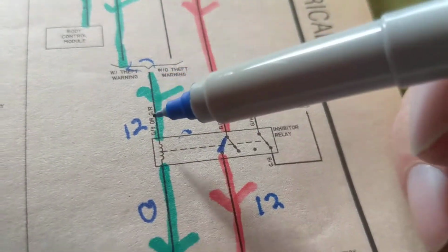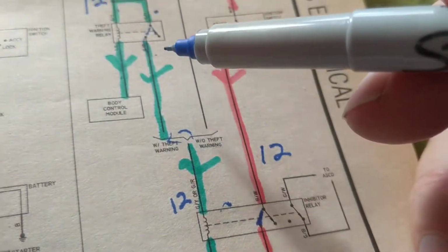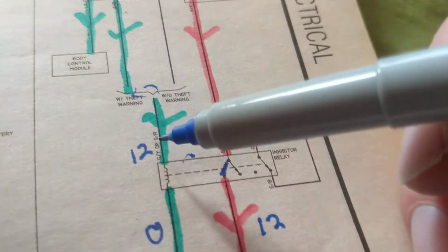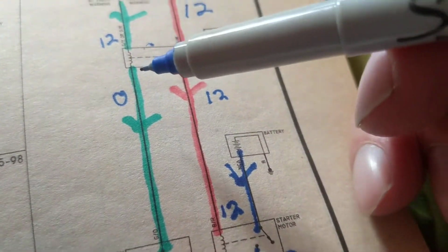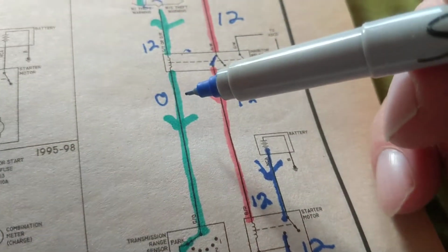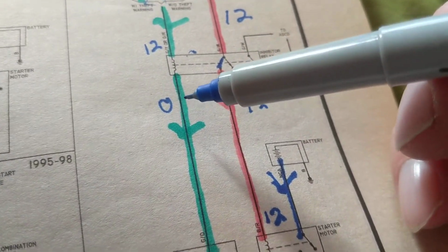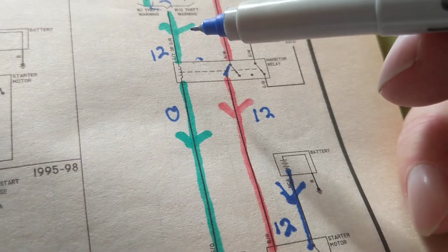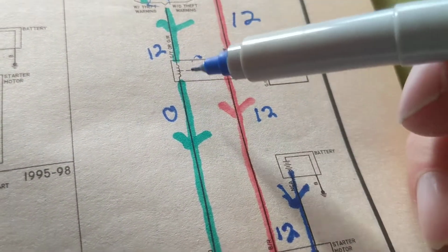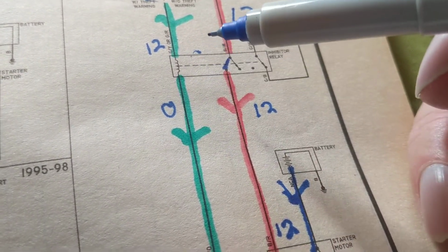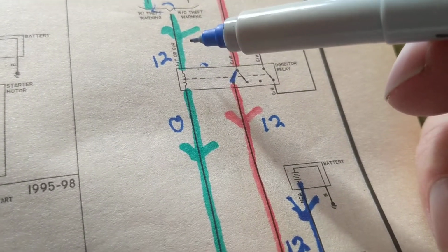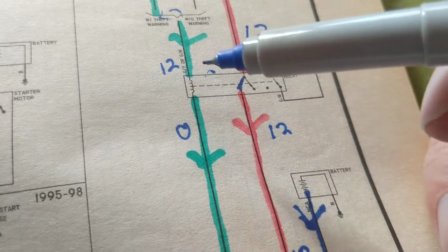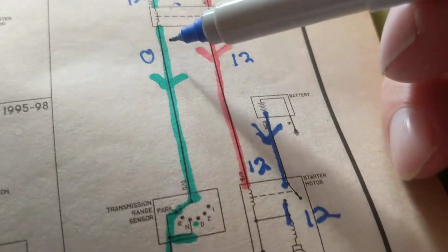We come over here, we have 12 volts. Again, we didn't lose anything. This is just a wire. We activate this with current, and as you see, I have 0 volts here. Why do I have 0 volts over here? I just made a statement indicating 2 things I needed to activate the coil, the control circuit as it is called: plus 12 volts, we have the 12 volts, and a ground.